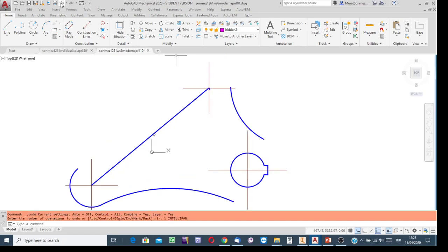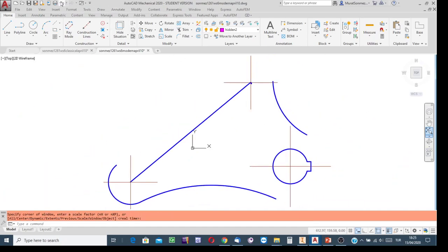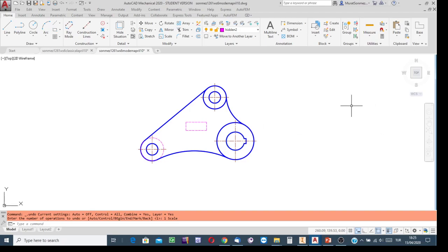Say oops, undo, and then, before applying the sizing process, undo. If you know that, or if it is your doubt that after applying the process you failed, then be sure that the reason of such a failure is the existence of dimensional constraints.